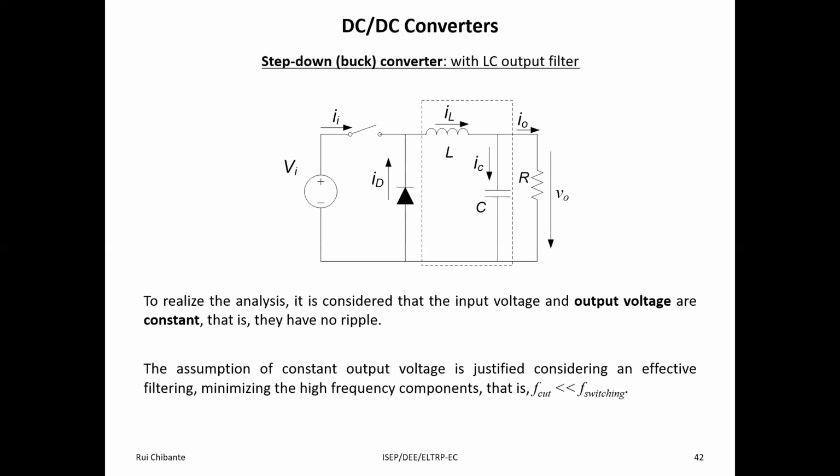So in situations where we want the output to be exactly constant in order to have a power supply for some electronic system that we have as a load, it is in these kinds of situations that we must use this filter that filters high frequency components and lets pass to the output only the zero frequency, and the zero frequency is equivalent to the DC component.